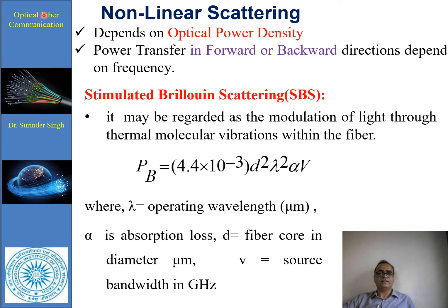Further, there is nonlinear scattering. Nonlinear scattering is caused by disproportionate attenuation at a high optical power level, and it causes optical power from one mode to be transferred to the forward or backward mode, in the same or to another mode at a different frequency.